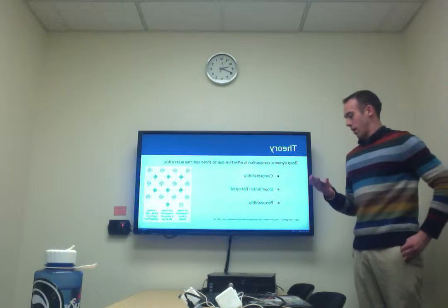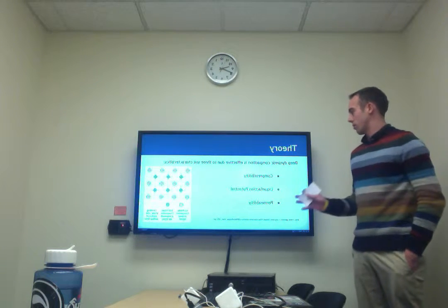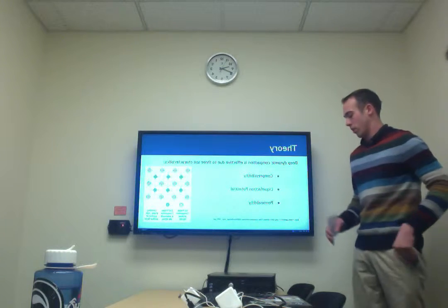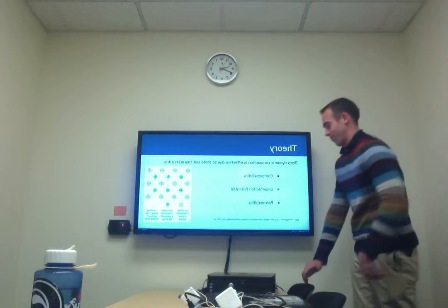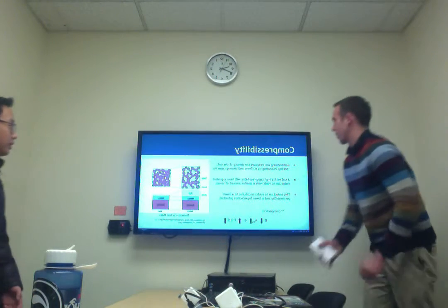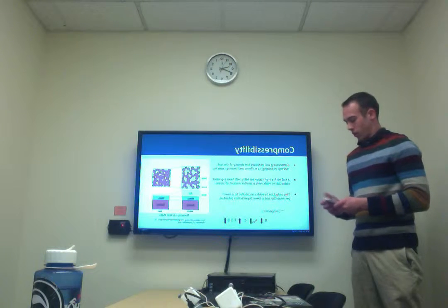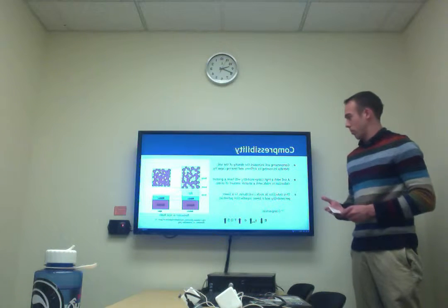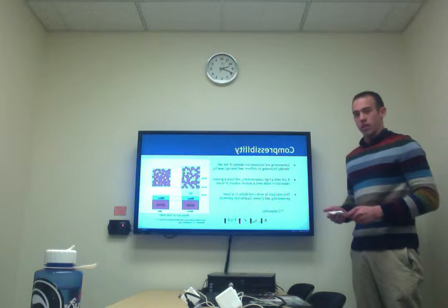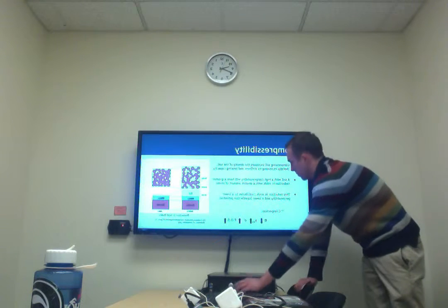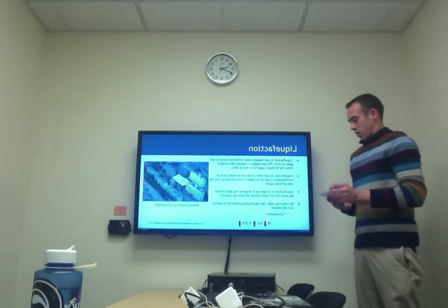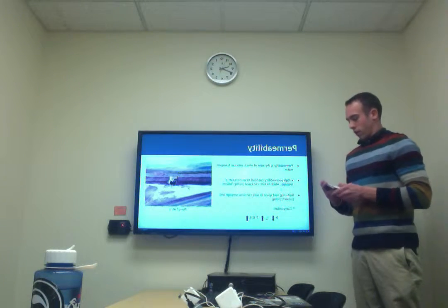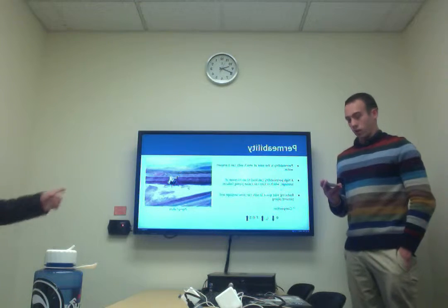So, the method of dynamic compaction affects 3 soil characteristics: compressibility, liquefaction potential, and permeability. On Monday, we learned that a high total pressure was needed to keep structures stable. A reduction of voids increases the density and therefore increases bearing capacity and the factor of safety. Liquefaction occurs when the effective stress of a soil goes to 0, giving the soil the property of a liquid.